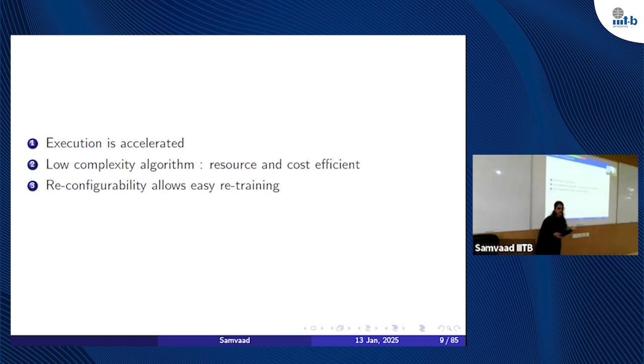And this reconfigurability of FPGA also allows for easy retraining. Reconfigurability means there are some resources on FPGA, we can use them and we can reconfigure them according to our circuits. That is a semi-customized design, unlike ASIC, which is a fully customized one, where you cannot change the circuit once it's fabricated.